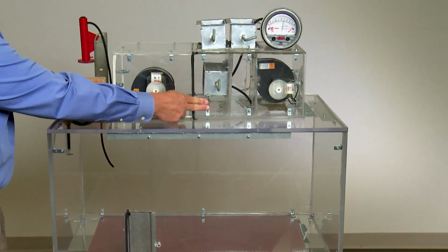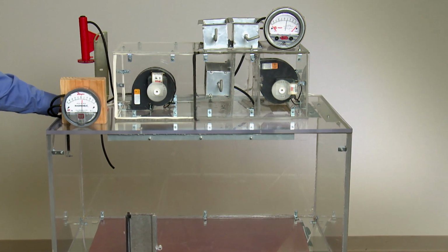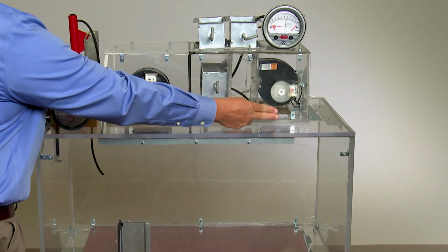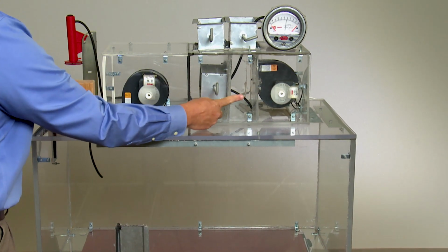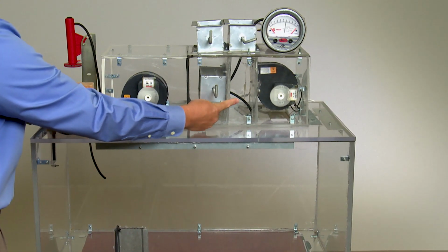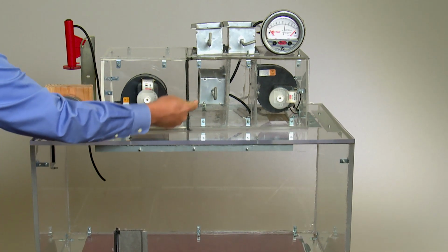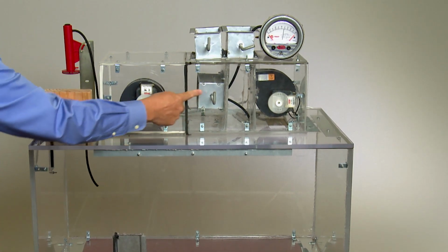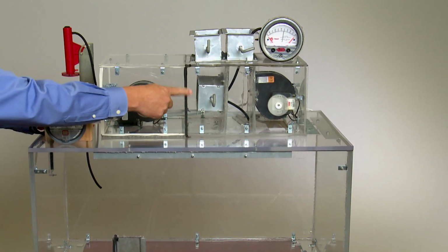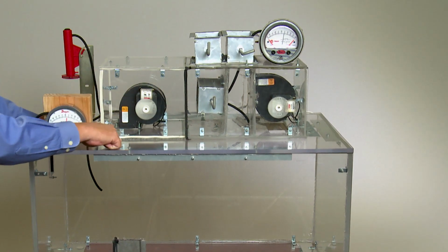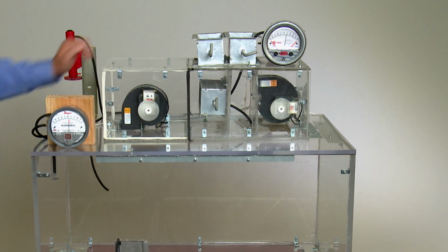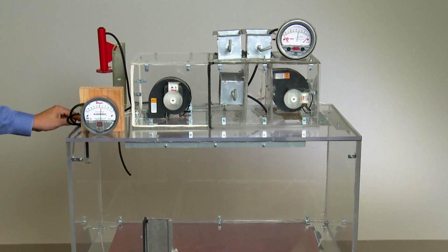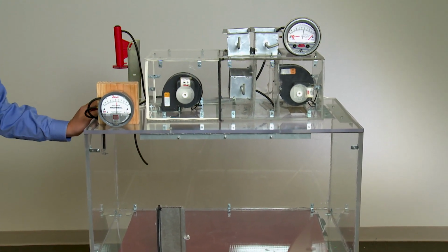Here we've changed this second module of our air handler again. This new module is equipped with a return fan, which is in series with a supply fan. This return fan draws air out of the building and pressurizes this chamber here. This air then either recirculates through the return air damper or exits the building through this modulating relief damper. Again, the recirculated air mixes with outdoor air in this mixing box and is then drawn into the supply fan. We've added a second pressure gauge to measure the pressure in this return air section of the air handler. As Chris mentioned, this pressure can be used to modulate the speed of the return fan.